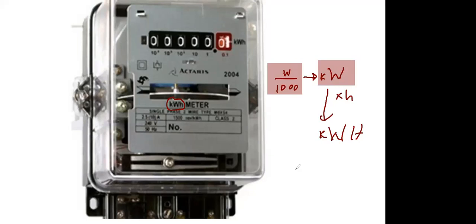Now one of the best examples, imagine I use 2000 watt. Normally you can check in your house the electric kettle, what is the watt value? So imagine 2000 watt. You use this electric kettle 2 hours per day. Now I want to find the per day electricity consumption by the electric kettle. How to find the number of units consumed? 2000 watt divided by 1000. Why divide by 1000? To convert watt into kilowatt. Multiplied by 2 hours. Very easy.